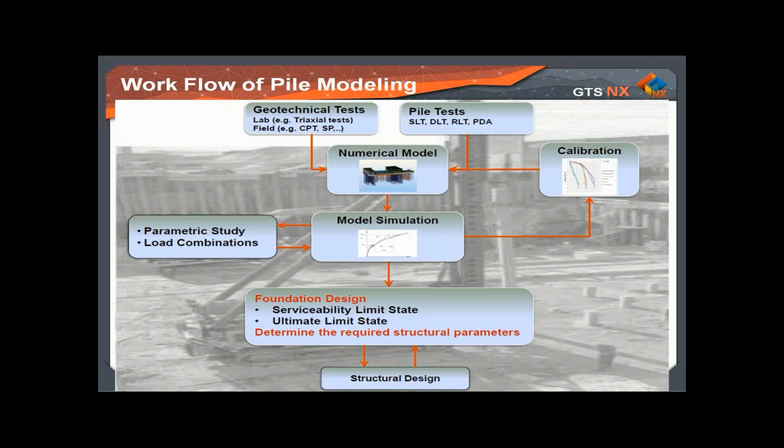You run your simulation and you will get results in terms of deformation, stress and strains, and forces in the piles, and you can also perform a parametric study. So, variation of the layout of the piles, the diameters and lengths and properties, and also different load combinations, such as structural load, wind load, earthquake load, and combinations of these.